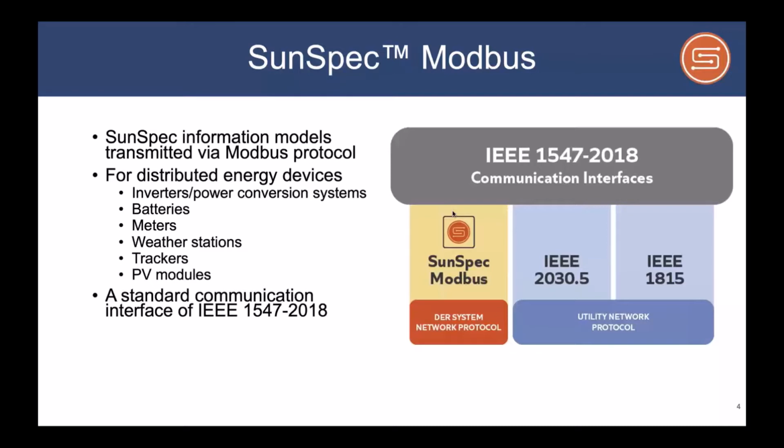The one right in the middle, IEEE 2030.5, is the communication interface for utility to system that is most often used for non-utility owned assets, thus comprising probably upwards of 98% of all assets that you see on the network. Once you consider that this includes things like residential PV and energy storage systems, and certainly will include communication to electric vehicle charging systems, and ultimately we believe this will even connect with electric vehicles. So you can see that there's many more connections there.